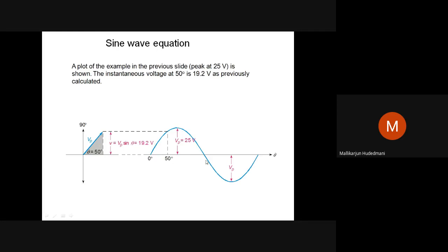We say progressive waves. When I say progressive, moving to the right side angularly, then this vector will rotate anti-clockwise when the waves are progressive. If the waves are retrogressive, if instead of going upward like this, I go in reverse, towards the left of my page, it becomes retrogressive. At that time, the vector representing such a quantity will revolve in the clockwise direction. Hope you are able to follow me. The vector representing the alternating quantity always has its reference axis horizontal, which is nothing but the 0 mark of this.